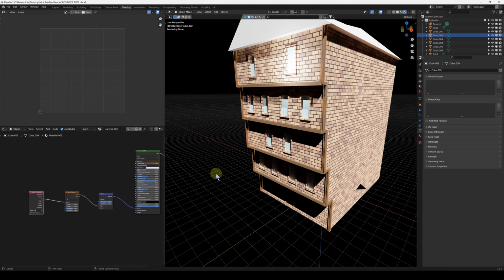So now this material, it's the same material, so this one is also now using UV coordinates. So that's why they no longer look the same. So what I needed to have done was, before I changed this, I needed to have pressed this button here, which tells it I want the material specific to this object. I don't want what I change here to affect that. So it needs to be its own material.